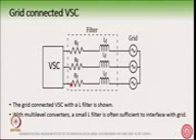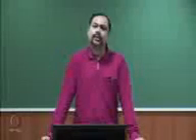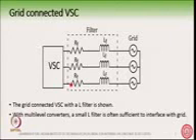We have seen that there are many steps in the waveforms and they have become highly sinusoidal, and for that reason a small L filter is often sufficient to interface with the grid. We will see this in detail.